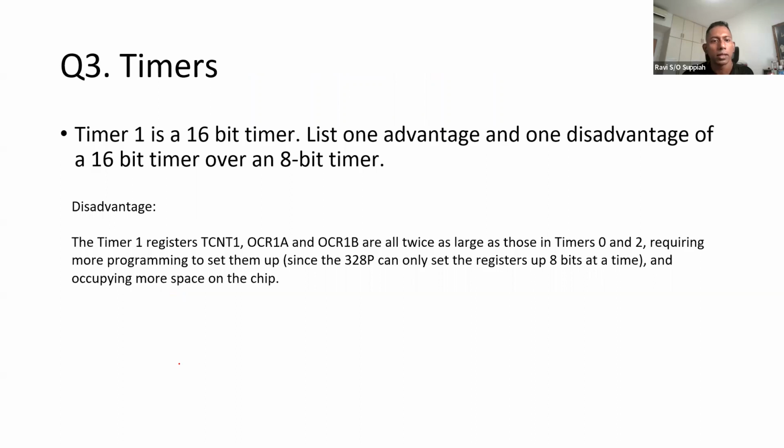Okay, so the registers are basically twice as large as timer 0 and 2, which means that you need to have more setup. In terms of the actual programming, you need to factor in that you need to configure 16-bit registers instead of the 8-bit registers.